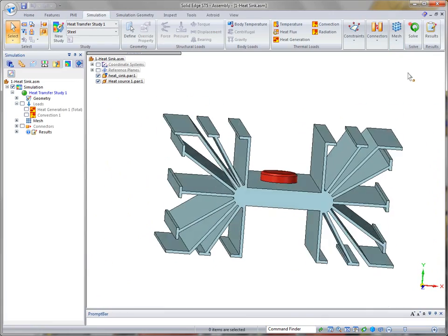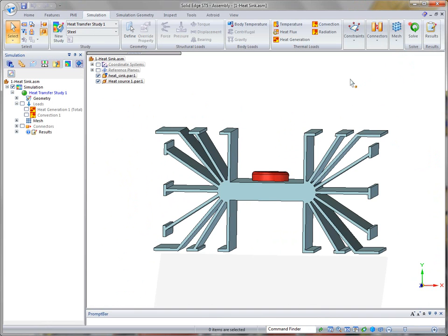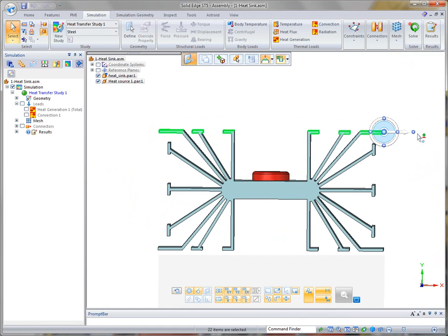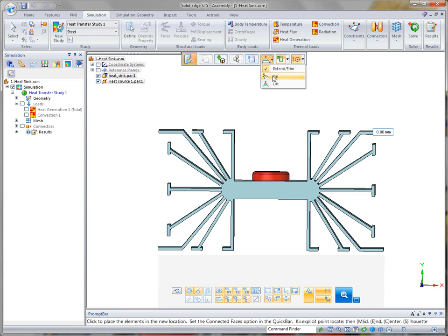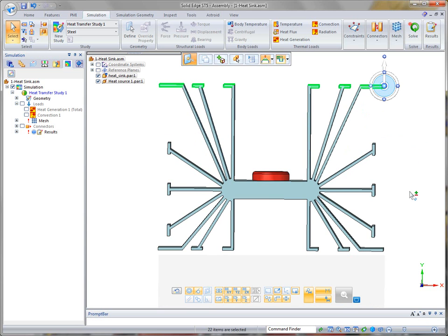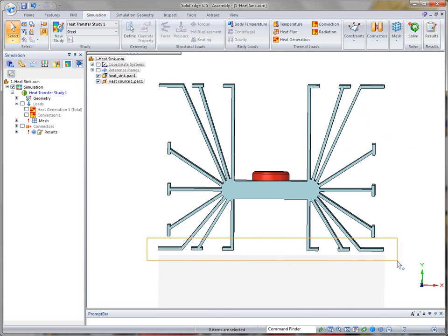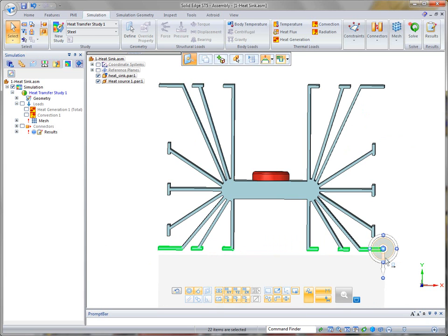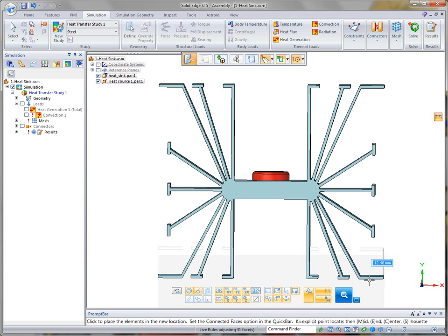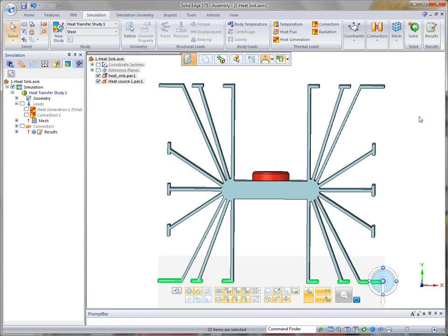Now, let's say I want to make a quick change. I'm going to go to a face select mode, select these top faces, and move them upward. I'm going to use the tip option so I can bring them up very quickly. I'm just eyeballing this; I'm not moving them in any particular order. I'm going to use the tip option here as well, so I can bring these down just to extend them out a little bit.